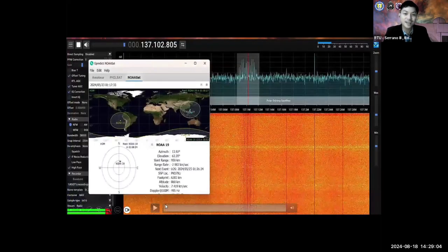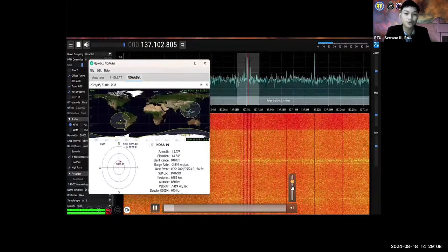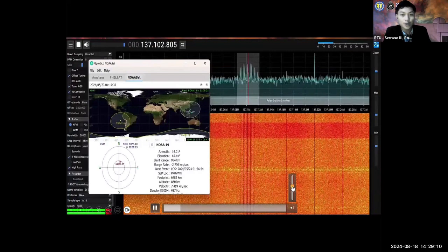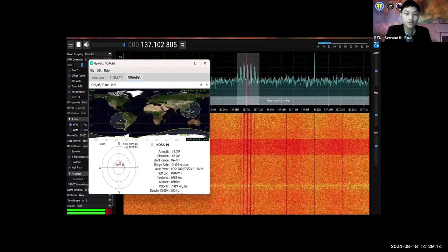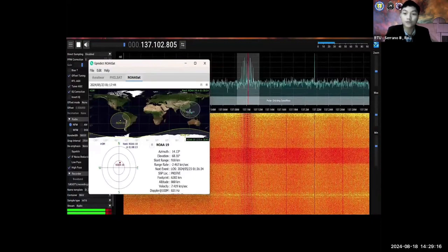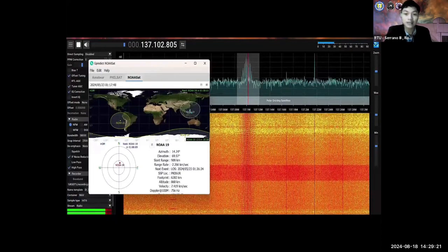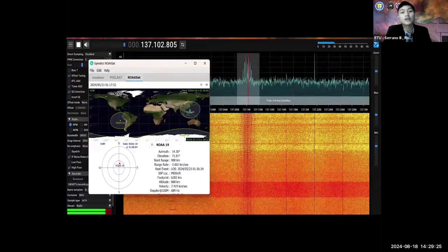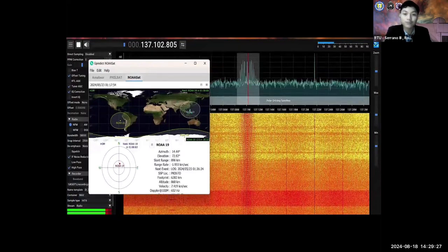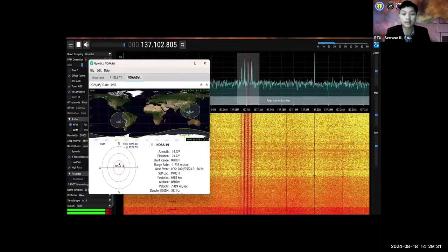Okay, so the next figure shows the overall process of the acquisition. On the left side, you will see our tracking software, GPredict, which we use to track the orbit and passing of the NOAA-18 and NOAA-19 satellites in real time. GPredict tracks the azimuth, elevation, slant range, the next event, the location, the footprint, altitude, velocity, and even the Doppler shift of the satellites in real time.